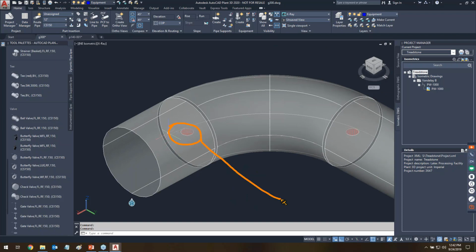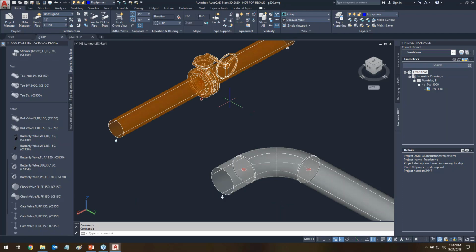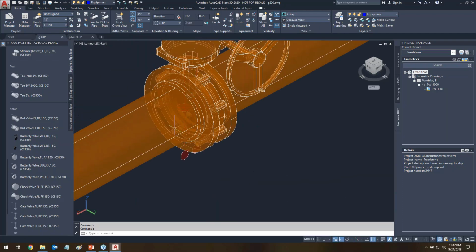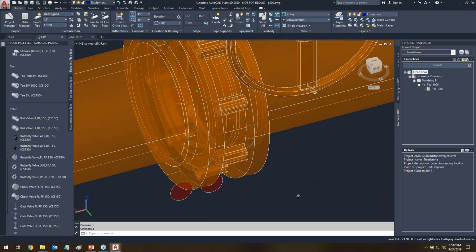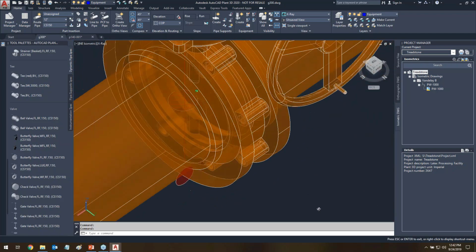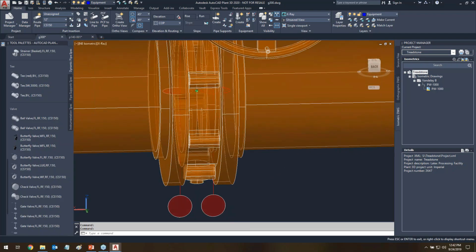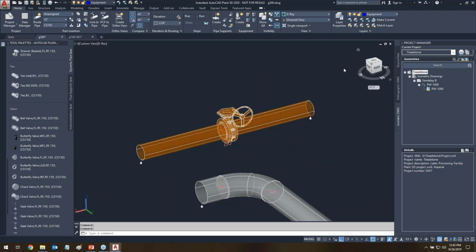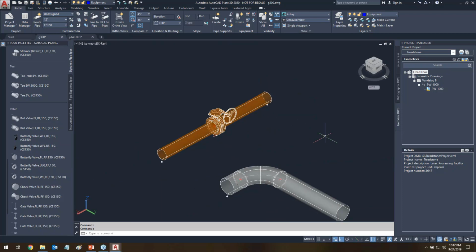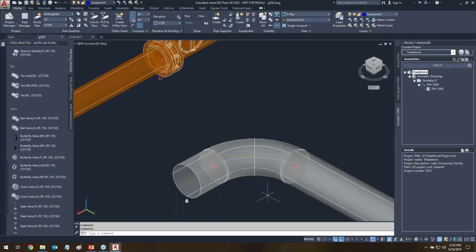So you have to have the plant weld display on to see it, but it's just the size of that particular dot wherever there is a connection, and that will show up in any connection. You can see it's over here in the wafered one, at these flanges, and at the bolt, right where the bolt set was. It's got those same connectors. So it affects not just welds, but connectors like flanges or gaskets and bolt sets and stuff like that. But that's what the weld dot does.